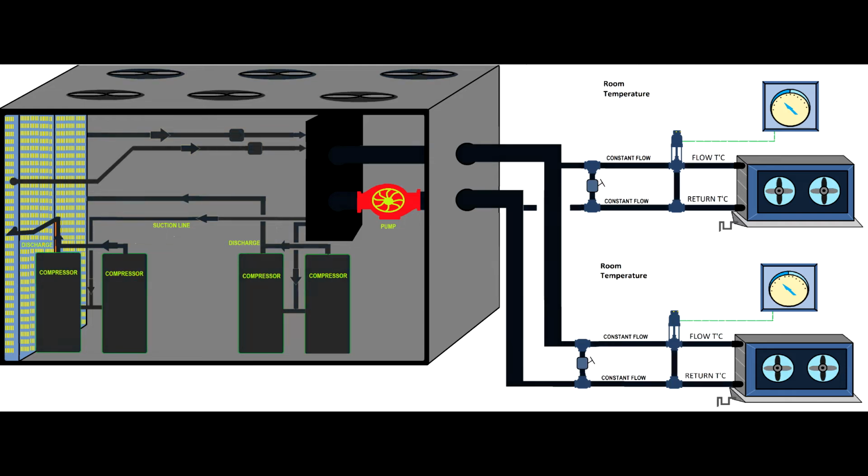This will be a very simple fault because you will immediately realize that you do not have cooling agent circulating through the system. You go to the chiller, you identify that the pump is not running, and then you have to repair the pump or any malfunction related to the pump, and then you will reinstate the chiller, so you will be able to have the cooling process again.